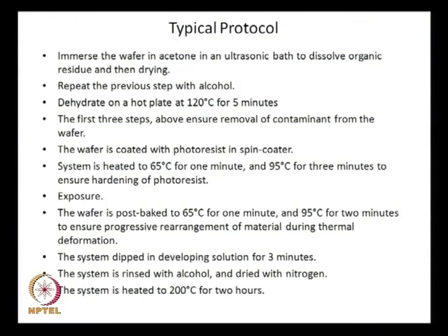So, a typical protocol would be to immerse the wafer in acetone in an ultrasonic bath to dissolve organic residue and then dry. So, take the silicon wafer that you have, 500 micrometer thick and 4 inch in diameter, and immerse the wafer in acetone in an ultrasonic bath.